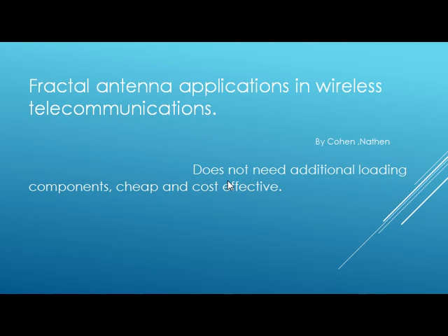Okay, stand by. Let me digest this. What is the RF frequency range for the fractal antenna? From 6 kilohertz to 600 megahertz. That encompasses so much RF spectrum that it will interfere with everything. If you start to operate this at kilowatts and at 91.5 megahertz, you'll wipe out the entire FM band. So people will know it.